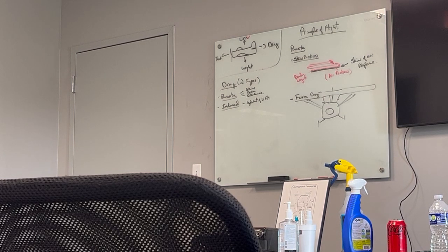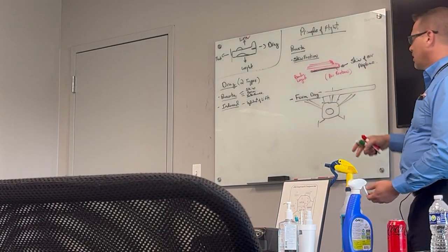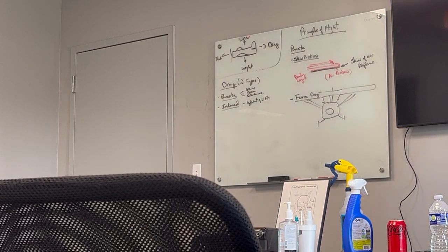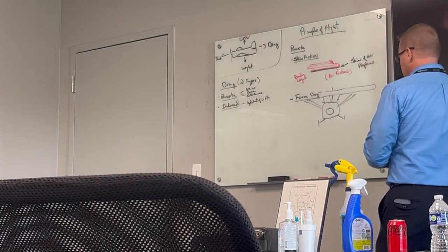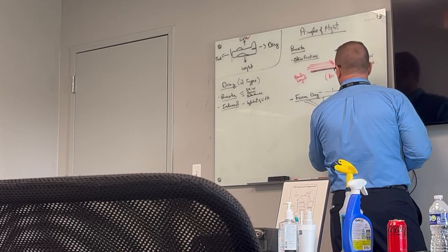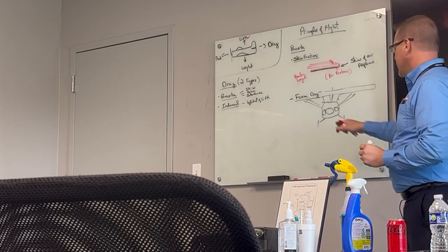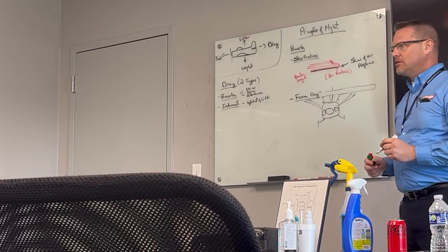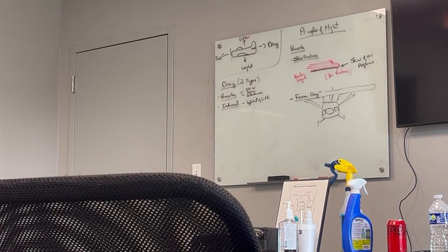We don't want to fly a flying brick. We want something that's aerodynamic, that's going to go fast and cause us the least amount of drag as we go through the air. So most of the surfaces on our aircraft are curved or molded, so that the skinny piece is facing forward. The biggest piece we have is our cowling out the front, which is relatively flat, still curved, but relatively flat, which causes a lot of form drag, as well as our windscreen. Anything exposed to the relative wind is what's going to cause your form drag.